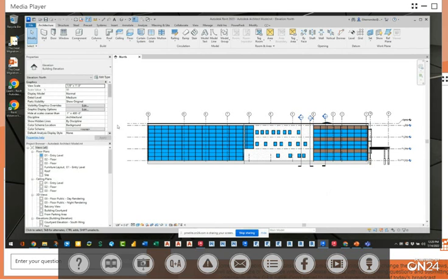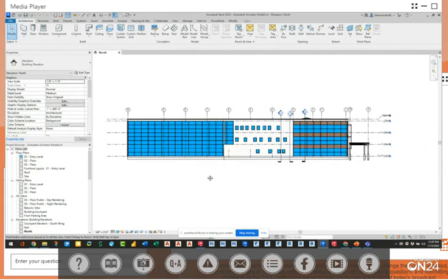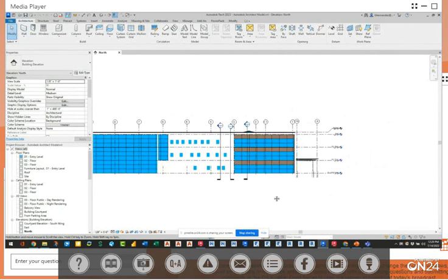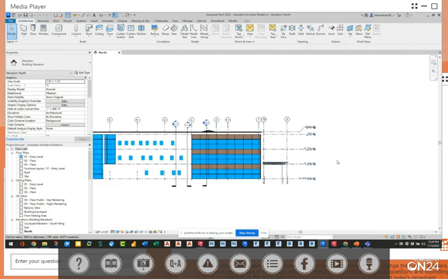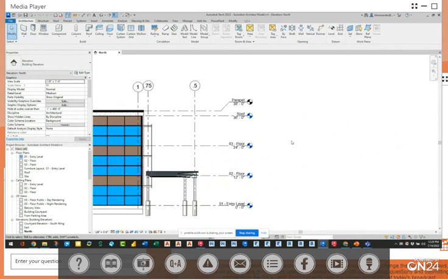So this is basically what your Revit projects would look like. You'll have your building here. Now, one thing that's different that makes this 3D from 2D are what you're looking at here in this elevation. These are what we call Revit datums or Revit levels. Here under the Architectural tab in the ribbon up at the top in our toolbox, we have what we call the Build panel. We have our Circulation, Model, Room and Area, and over here on the end is the Datum panel.